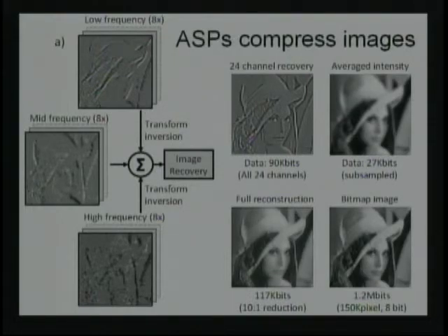Now, a 10-to-1 compression ratio is not a great compression ratio, but there was no computation in this. All of the convolutions were done optically for 0 power. And then the rounding you do in your own analog-to-digital converter on board. So you actually make a lower power analog-to-digital converter because it's doing fewer bits. And so you can do all these operations for reduced power on your imager. So although the compression is not as good, the power consumption is mind-numbingly better.